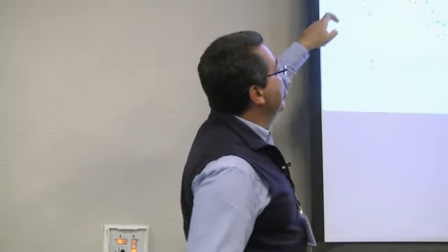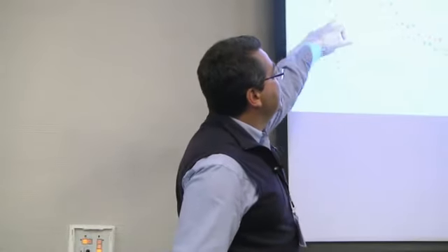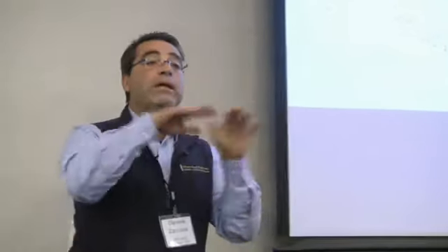You can see 2017, we got a different situation, 2018, another different situation. And here is the weekly average crop coefficient that we derived in the north and the south. This is a weekly average, so it's supposed to smooth all the fluctuation. But we see also a clear trend there, and things are not following exactly net radiation, because this is not a level area. So how do you manage irrigation here? When we have to provide information, we say, well, probably the best thing to do is measuring and applying water according to a certain strategy. Okay?